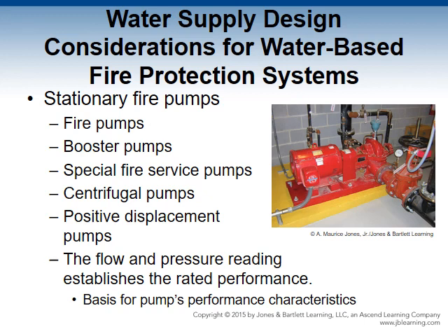Performance rating characteristics. The flow and pressure reading established the rated performance, which is the basis for the overall performance characteristics of the pump. The performance criteria are stated in gallons of water flowing, GPM, at predetermined pressures, PSI. The ability to pump is determined by comparing the rated flow and pressure readings with 2 other specific performance points on a graph to create a performance characteristic discharge curve.